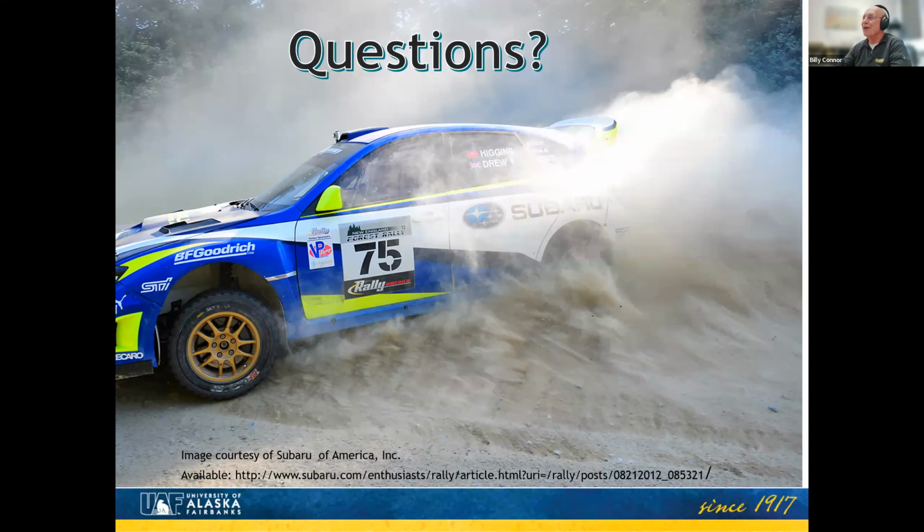And you talk to any of the folks at Alaska DOT, once you pave the road over permafrost, the workload for them goes up dramatically. It's just a trade-off there. So if you really got serious permafrost, the harder type surfaces are probably not going to be very attractive for you. Any other questions that I can answer?